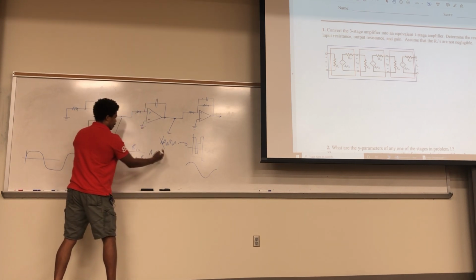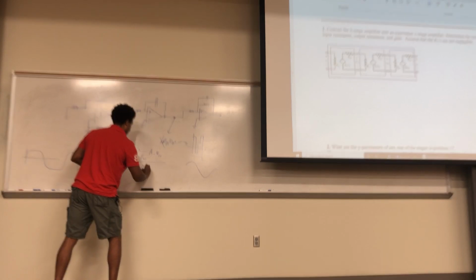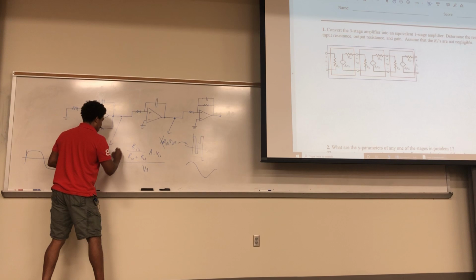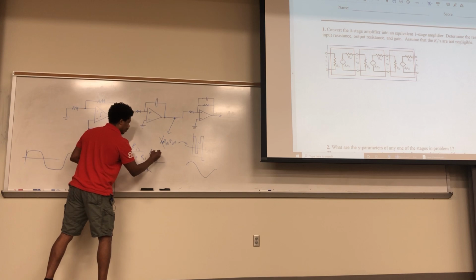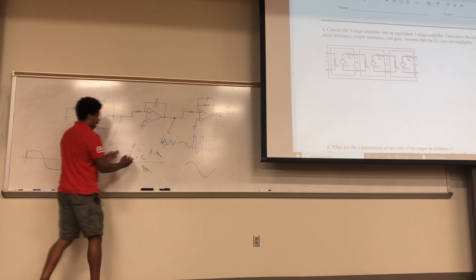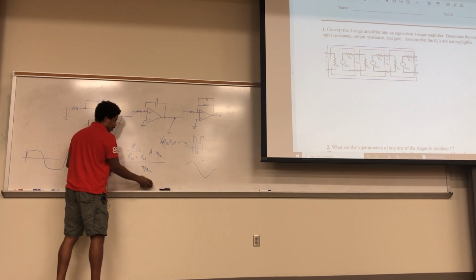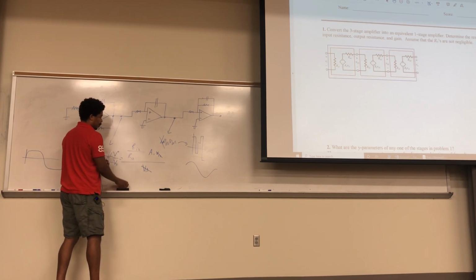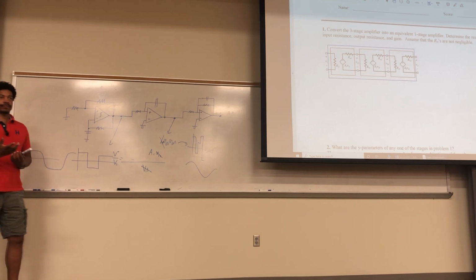Okay, that's the voltage. That's output. The input is this right here. So Vout over Vin equals that. These two would cancel out, right? Now, if Ro1 was negligible, you could say, well, it doesn't matter. Then that means that this over that just becomes 1. And so that's why if the ROs were negligible, you would just call it A1. Okay?